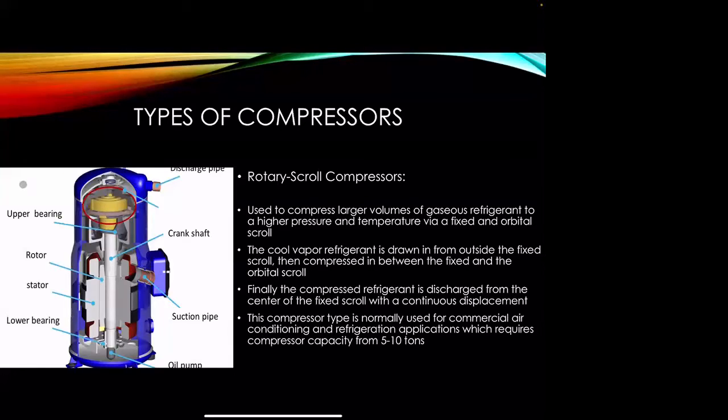These compressors we'll typically see in commercial air conditioning applications, refrigeration applications as well. And these are capacities of 5 to 10 tons. You'll actually see this type of compressor here in the new Carrier Evolution or Bryant Evolution Carrier Infinity 5-ton Greenspeed Extreme.